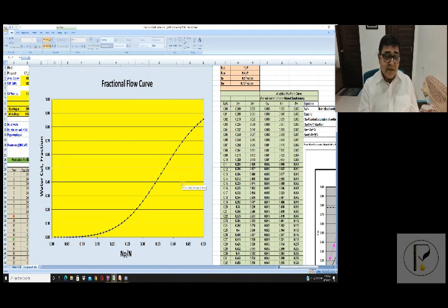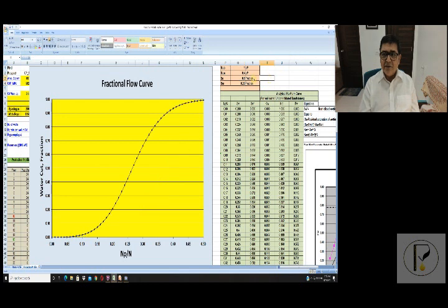I'm seeing some projects coming up very close in India, that in the tertiary stage, a carbon dioxide miscible project will be undertaken, obviously to increase recovery from 40% to 50% plus, and additionally getting some more benefits of carbon sequestration as well. So you can see how to rejuvenate a matured field when the oils are very light and volatile.